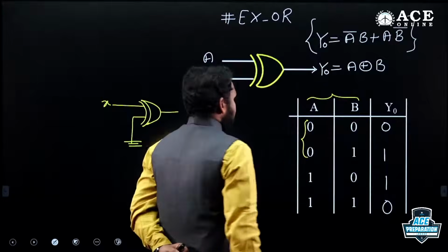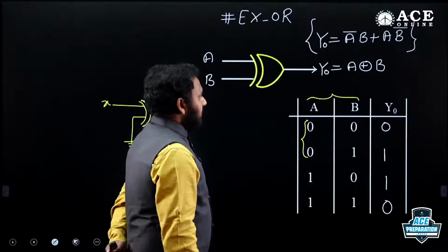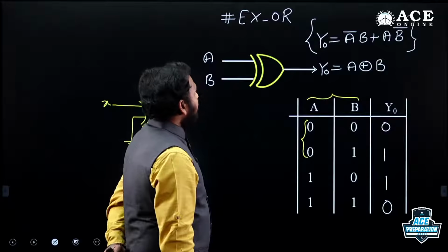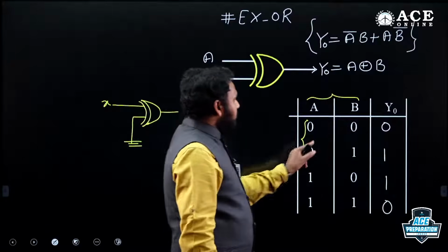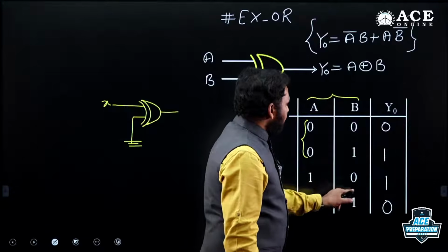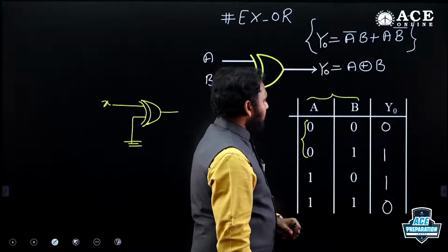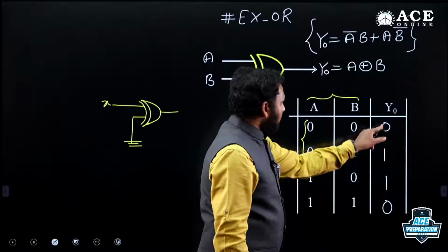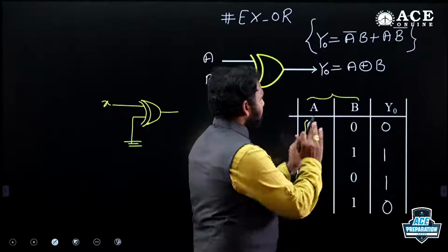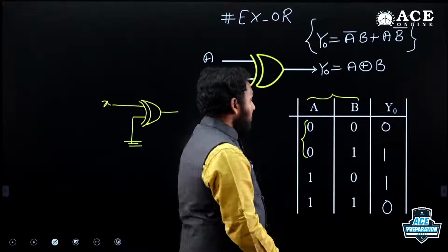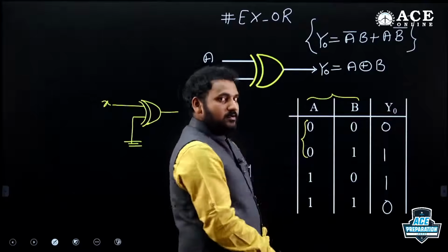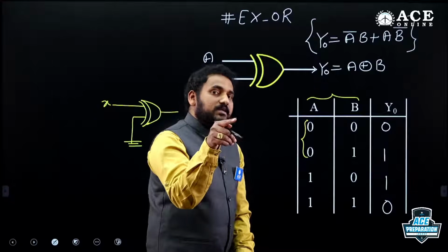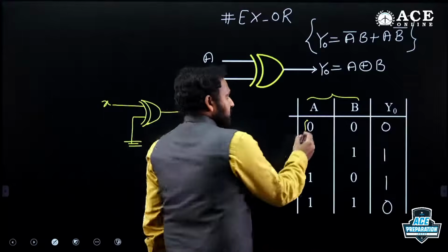This is an XOR gate. In the exclusive OR gate, if inputs are complements of each other, it produces logic 1 at the output. If inputs coincide, I mean are the same, the output is 0. That is the basic truth table. But if one input is 0, then what is the relation between the second input and the output? See this.